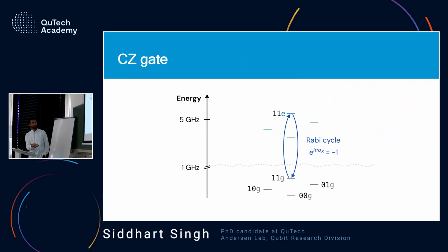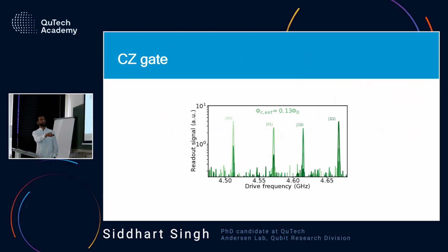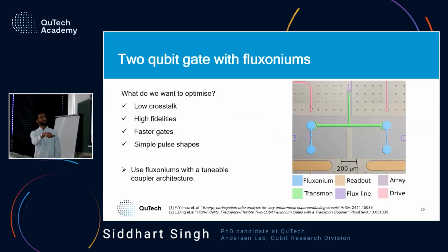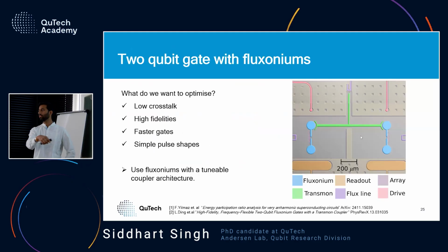So you can see here that the first thing is the placement of these levels. The placement of these levels depends on the energies of these individual qubits, because you are using an inductor, a capacitor, and a junction to make individual qubits. So what's critical is that you are able to target all three close to the values which you want, in a way that these four levels are still far apart from each other.